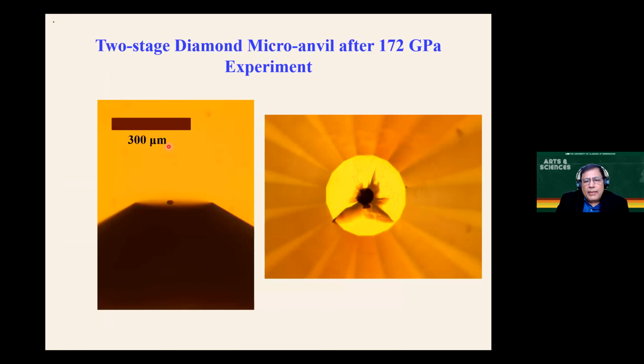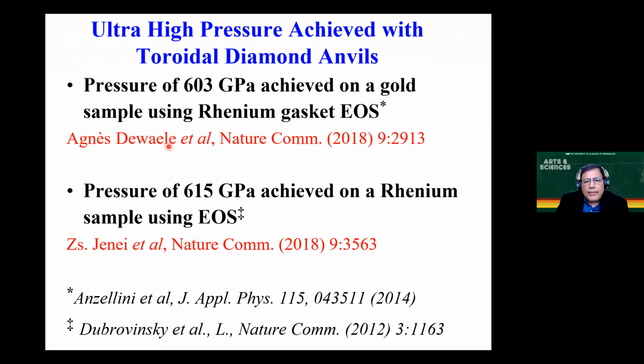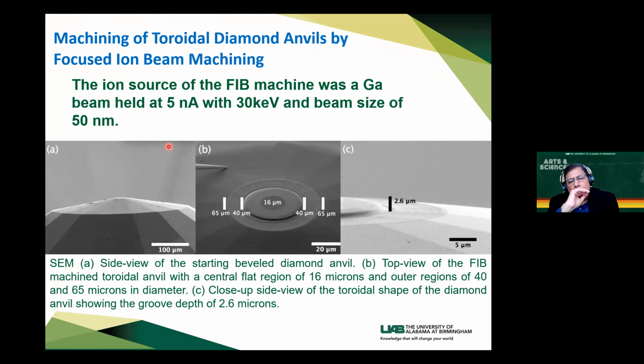Yeah, I think that's a good question. So remember that in a beveled diamond, if you have a culet like 20 micron, by the time you get to around 250, the diamond is cupped. So it is bent inwards. The basic idea is to compensate for that cupping by making a dome in the center, along with some flattening on the side.